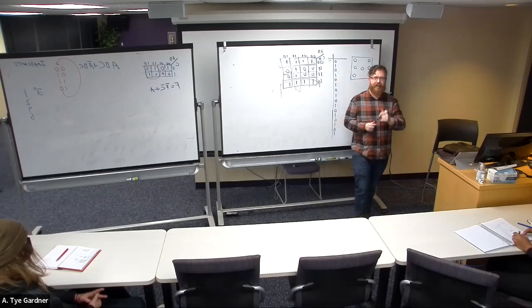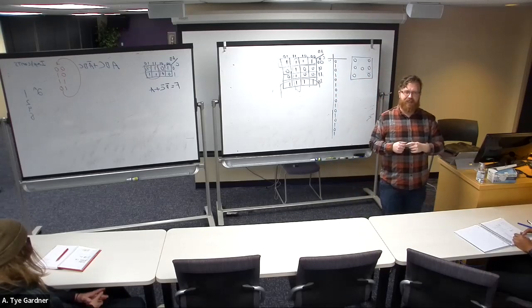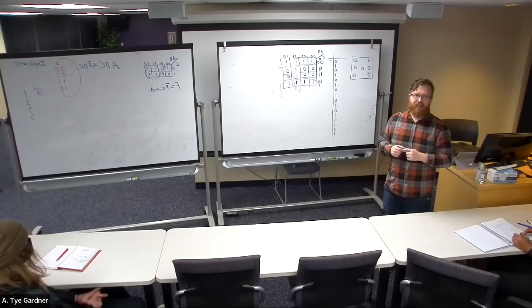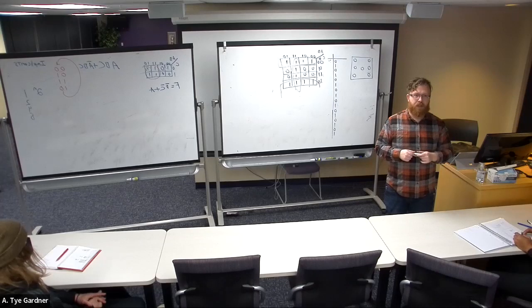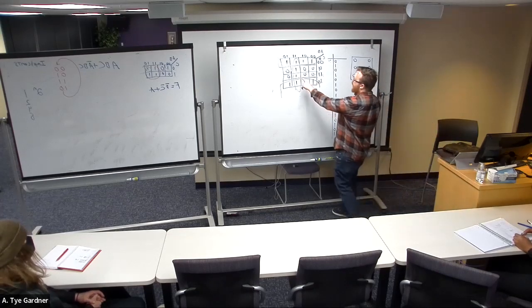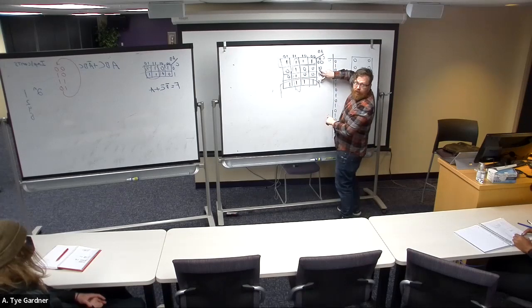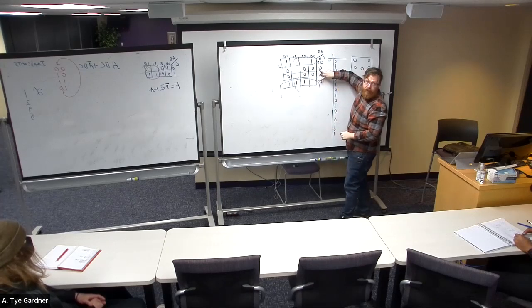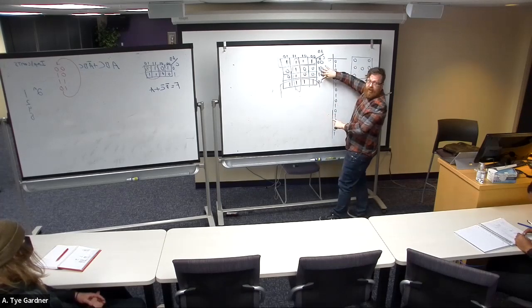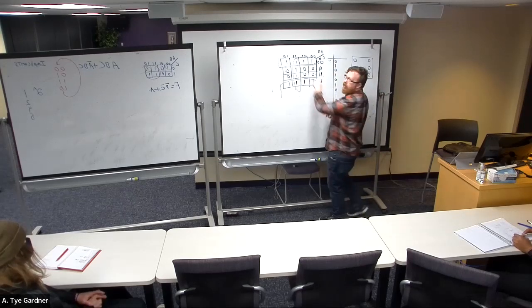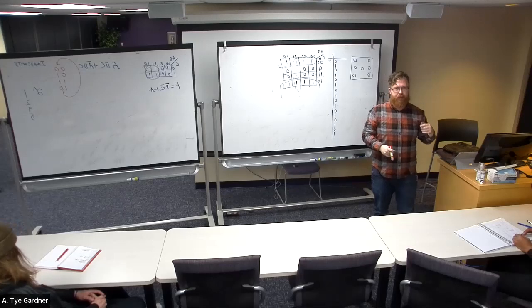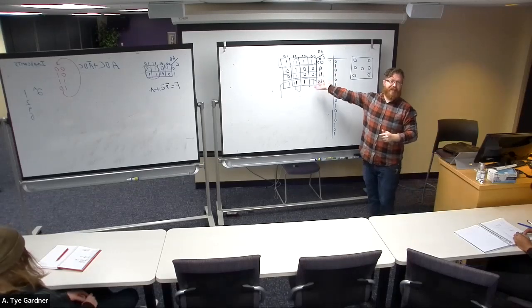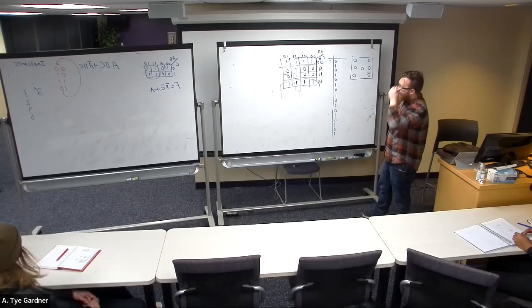All right, the vertical column. Yeah. I'm just wondering, would you want to circle all 4 of them instead of just the 2 center? Yes. What does it change? The number of variables that don't change, right? Because if I circle the inner 2, then D doesn't change, and A and B don't change, so there are 3. Whereas if I circle this whole thing, then that D does change from here to here, so it's just A and B. So it's actually removing one of the variables, which is why I say just circle the biggest things we can find and then move on from there.